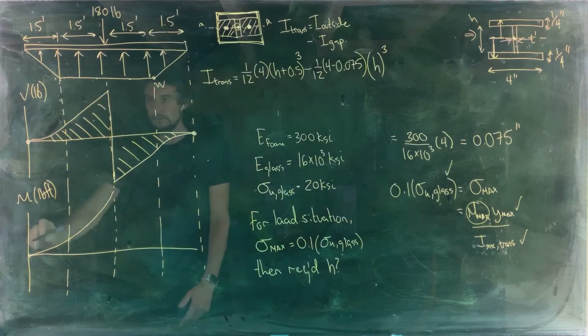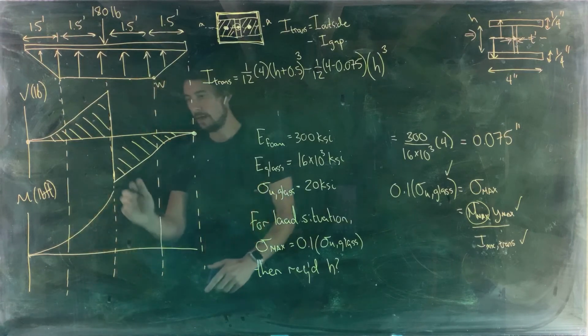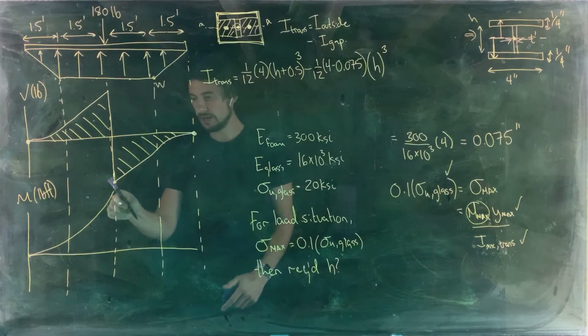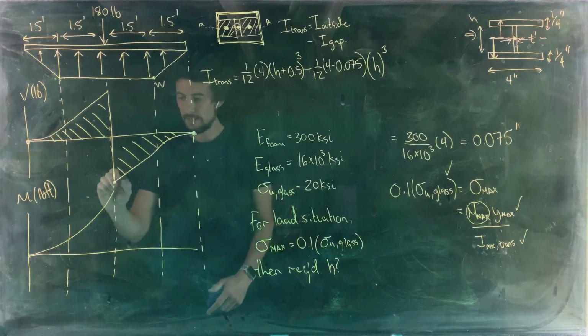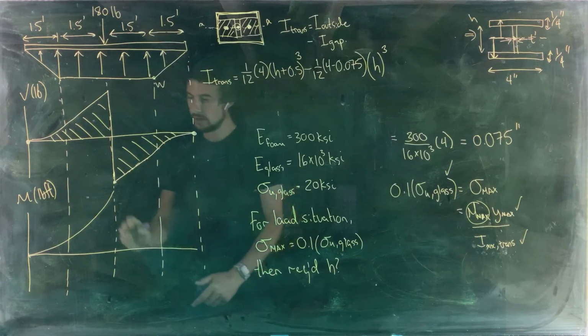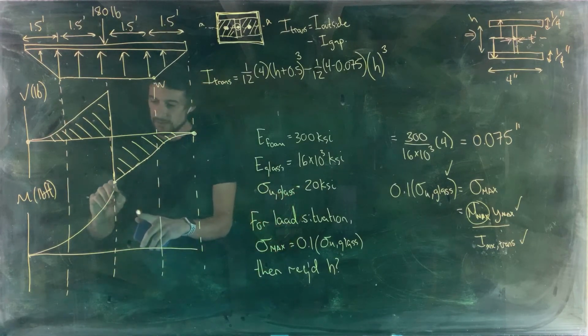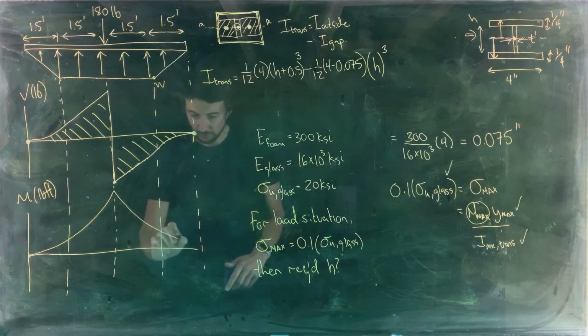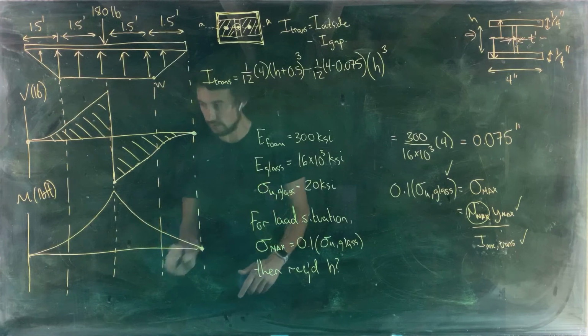Okay. So increasing positive slope. And then the shear values flip to negative. So the slope of the moment diagram needs to flip to negative, and the values of shear become increasingly small negative values, so the slope has to become an increasingly small negative slope. So matching curve back to 0.